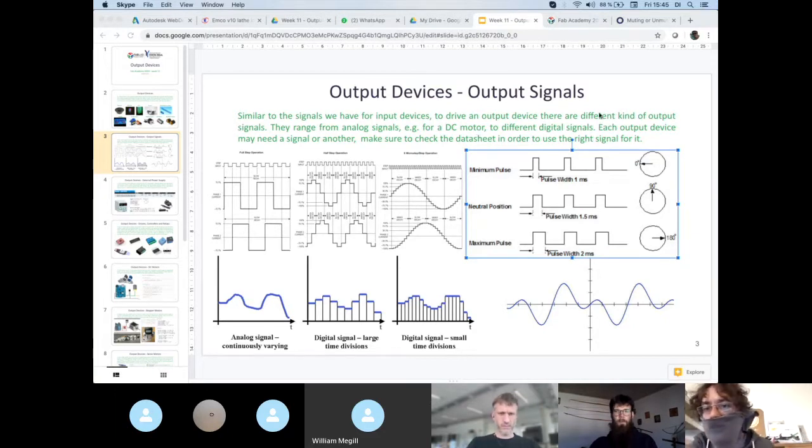So for servo motors, this means it will be at 0 degrees, and for brushless motors, most likely this means it doesn't spin, it's stopped. 1,000 microseconds, or 2 milliseconds, sorry, means that it's 180. I will tell you, for example, in the drone, it's like this. In the big brushless motor that we use for the project from Karsten, who made an electrical scooter, it's like this: 1 millisecond is not spinning, 2 milliseconds is the maximum speed.